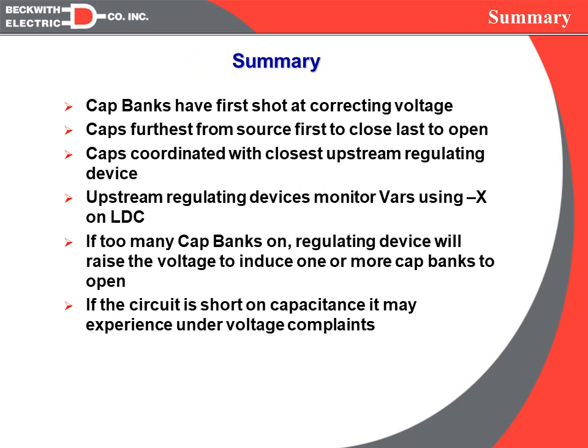So in summary, if we're going to go with an IVVC system with no communications to the downstream devices, the first thing we're going to do is have the cap banks have the first shot at correcting the voltage. So we want our capacitor banks and our regulators to be timing at the same time, but we want the capacitor banks to always have a shorter time delay, and therefore they will always be the first to correct the voltage, and hopefully we're going to reduce the number of operations on our regulators and our LTCs.